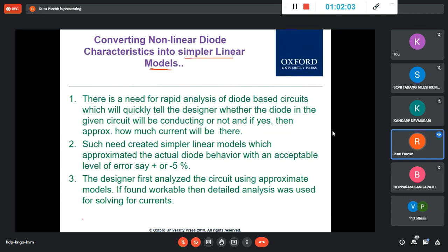Now let's say you want to study diode applications such as a rectifier, where you will have very high voltages. We are going to study all those circuits slowly. But when you have very high voltages, you don't need very precise values like a 0.7 drop or a 0.5 drop, or milliampere current.